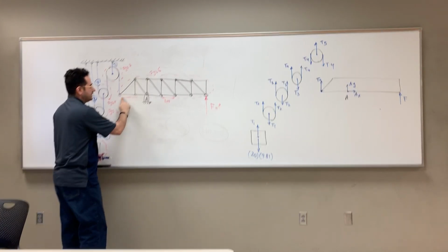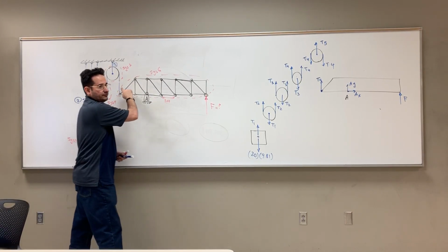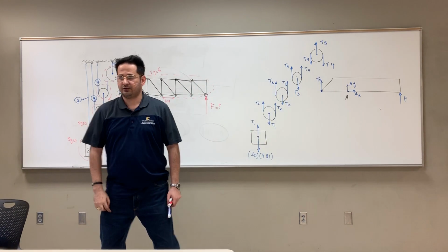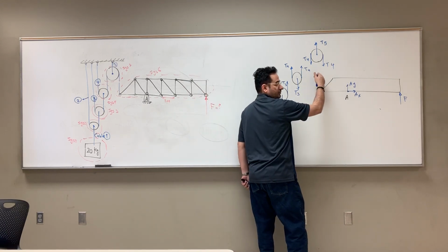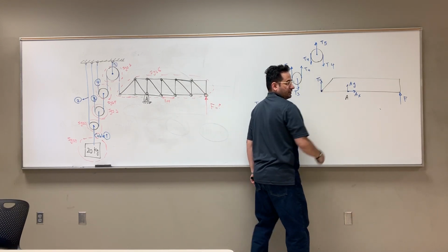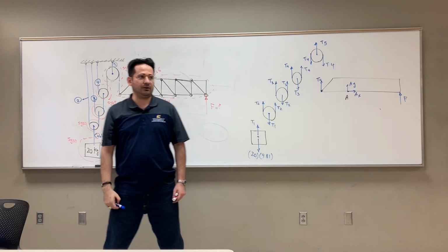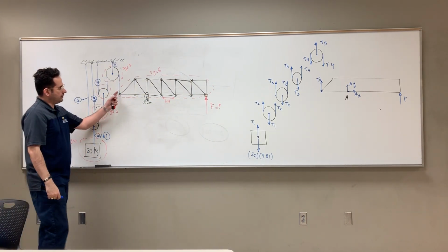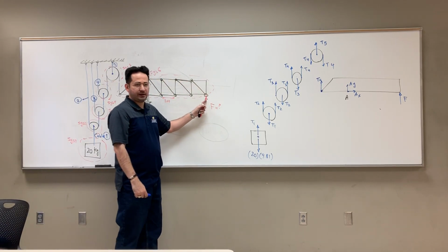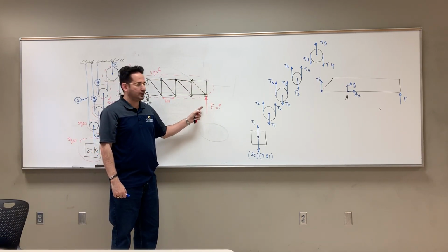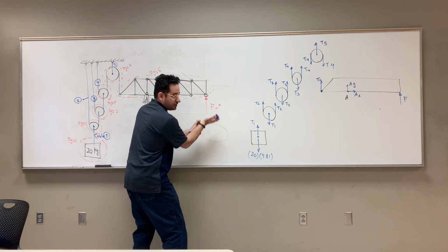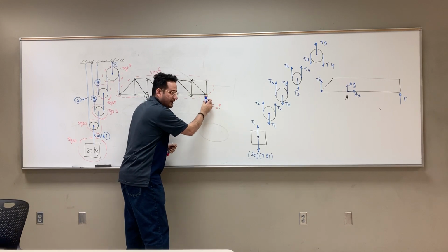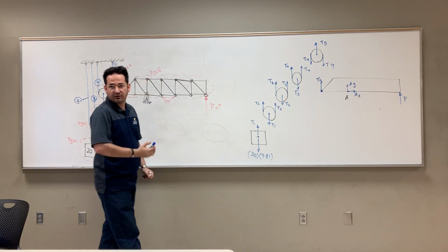Now if you walk around here, the first thing you cut is the force in that cable. And we designate it by T4. So I just use this value, but just flip the sign, because it's the same according to Newton's third law of action and reaction. Right? T4. You walk around and the next thing you cut from the surrounding is F, because somebody is pushing it, right? So if I want to isolate this, you have to put this effect coming from the outside world. Somebody is pushing it.